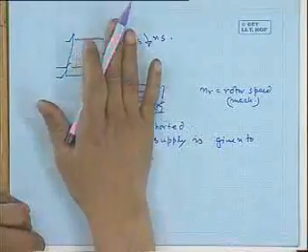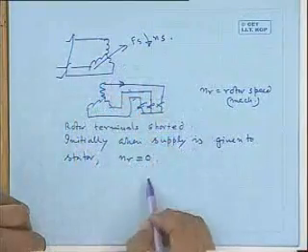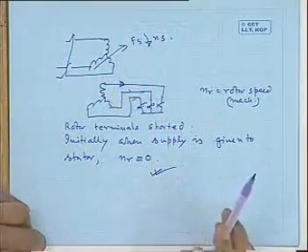So there was no question of any torque production on the rotor conductors, because you require B, I, L; L is there, but I was 0. But now it may appear that the rotor is carrying current, and it is already placed in a magnetic field, so it should experience some force or torque. Anyway, this aspect I will take tomorrow. So today I stop.